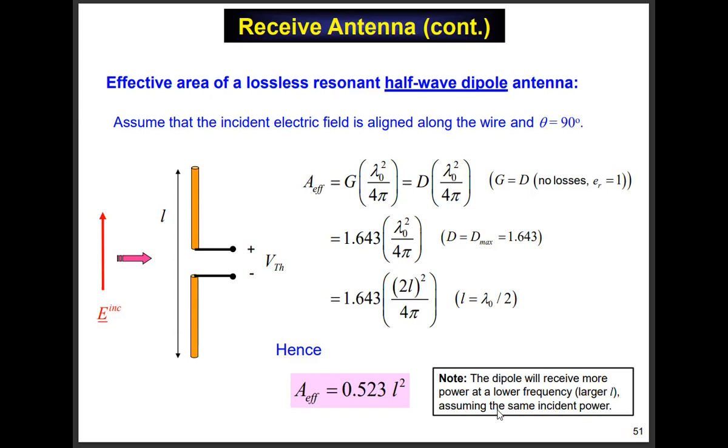By the way, it's an interesting side note. Remember, any resonant dipole wants to have a length that's lambda over 2. So I showed you pictures of monopoles, that could be the big tower, hundreds of feet, or a little thing on your cell phone, right? It all depends on the frequency. So I hope this note makes sense. Look at the formula here.